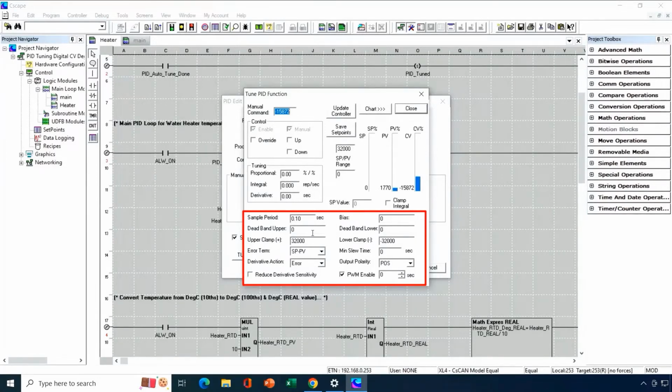You'd set a deadband if you didn't want your control value to be moving around a lot near the set point. In my case, I have a solid state relay controlling a heater, and I have no concerns about any kind of mechanical wear of my devices, so therefore I'm not concerned about a few extra cycles on the solid state relay, and I won't set a deadband.